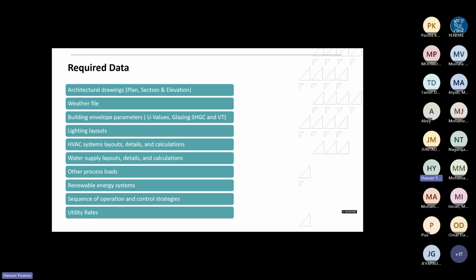And make sure that you understand which file version you're using and what years that file represents, because some of them would end at a certain year that may be already 15 or 20 years ago. So you need to use the latest ones. And these are not used for peak load calculations. They're mostly average years, say a 15 or 20 year average. They would still give you a good indication for the peak, but for the peak conditions, it's better to use peak values from, let's say, the ASHRAE database, or if you're in Dubai, you're going to follow what the municipality will tell you.